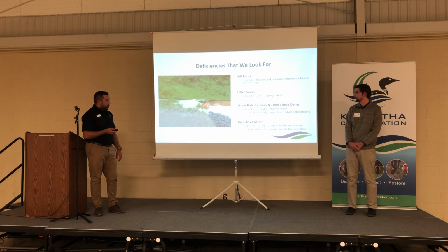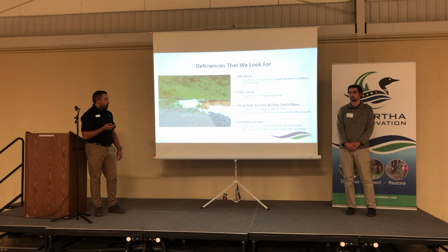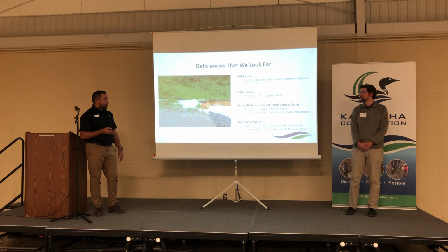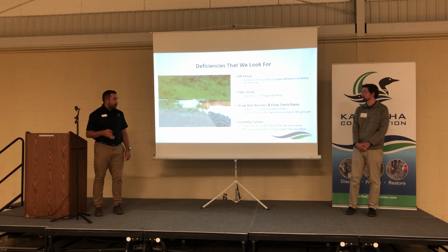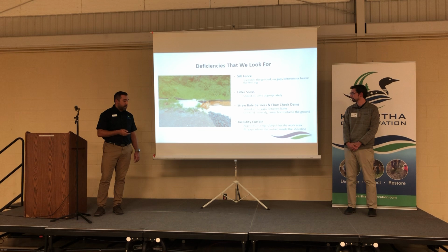And with turbidity curtain, again, if that's in use on site, we'll make sure that it's being used appropriately, with the appropriate length and depth for the work area. We usually like to see it butted up against the shoreline, especially since there'll be that gap underneath in this type of application, where it's used on the lakes to allow any fish or any other species to make their way out.